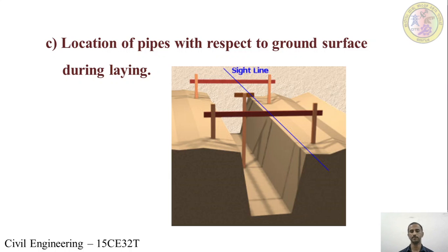If the water supply line is to be excavated, laid near a sewer line, a horizontal distance of 300 mm and vertical distance of 300 mm minimum is maintained. And these pipes are laid from the existing foundations at an angle of 45 degree away from the foundation.